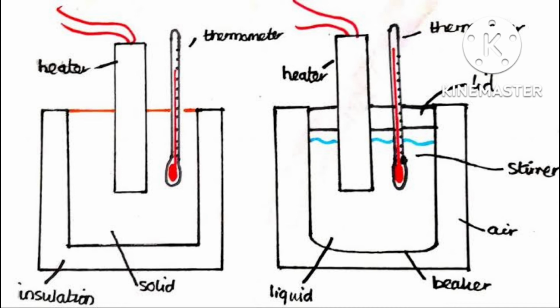The formula you can usually use is Q equals Cv into delta T. But here a minus sign you have to use, because the system is losing heat. So Q is minus Cv into delta T. The Cv value is given, and delta T is 299 minus 298 Kelvin, only 1 degree change. Then it will be minus 20.7 kilojoule into 1. Now you know this Q value. It means what?